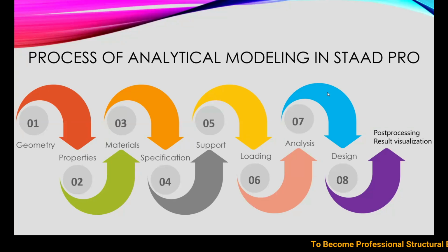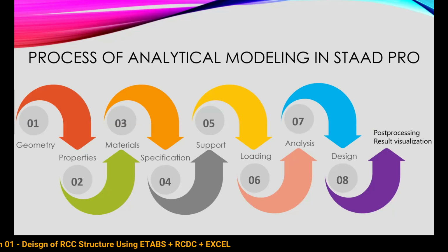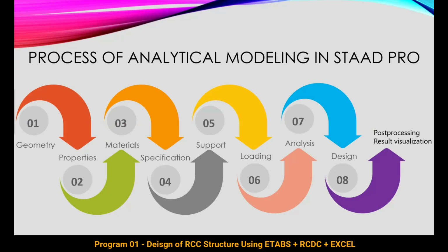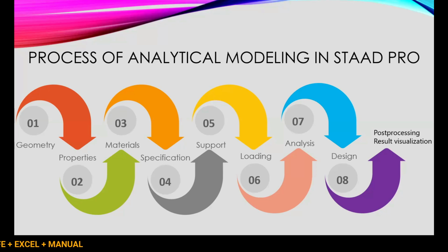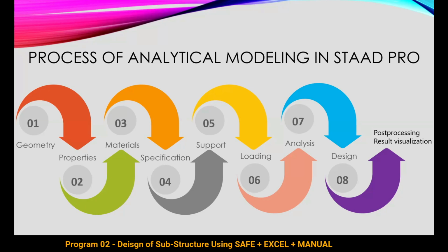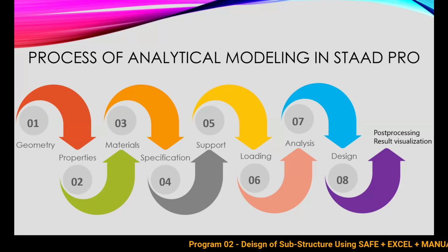One of the questions asked is, in steel structure, is a member designed for elastic design or plastic design? So generally it is designed for elastic, but if there is a requirement from the client, or if there is any additional requirement, then we go for plastic design. And also it depends on the cross section. If the classification of the cross section comes under class 1, then the Indian code allows us to design it as a plastic member. When it is class 2 or class 3, or it is a slender member, then we design it as an elastic member or according to the effective section. This depends on the cross section, and also generally it's designed as an elastic member.